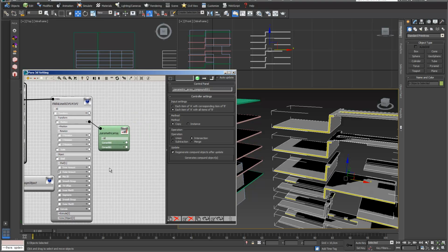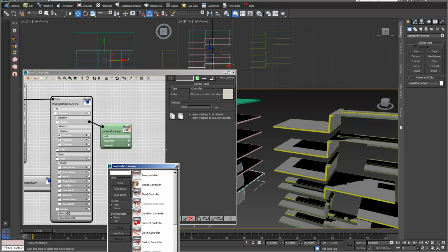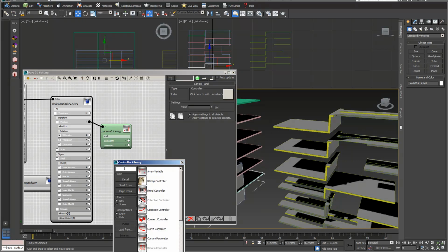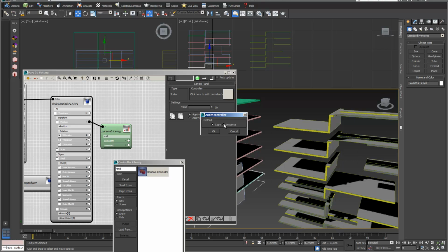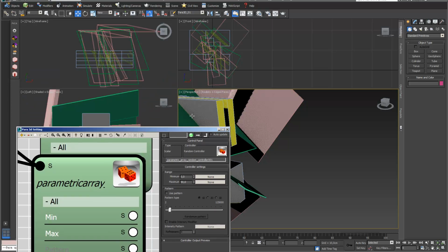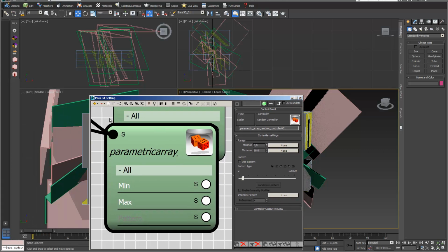And you can also do things like this. You go into rotate, and you just want to rotate your elements. Okay, here I have to deselect obviously my outer amount, that's really important. So I just ticked X and Y, and I just pull it and I add something like a random controller as an instance, and change from radius 0 to radius 90 degrees. I go into update, and obviously something really chaotic more or less came out of this, but you can also use this one.